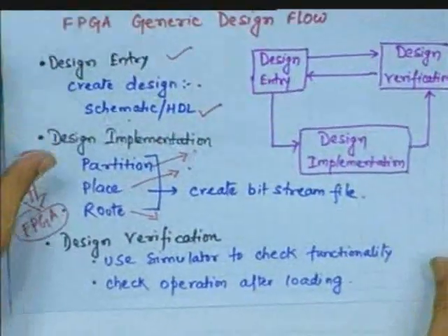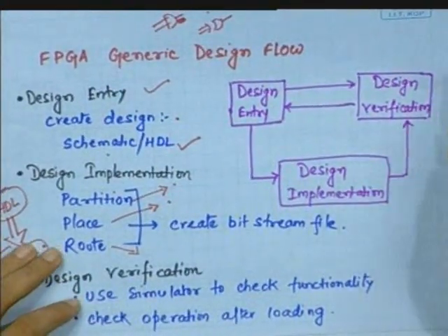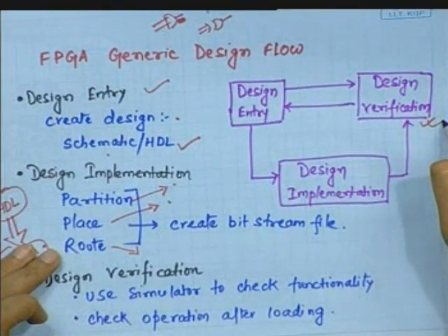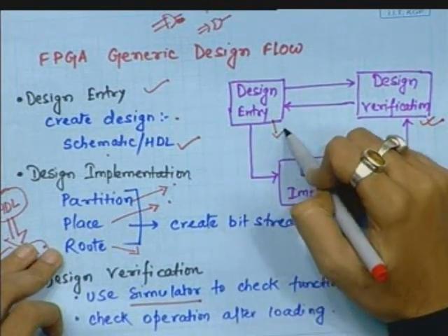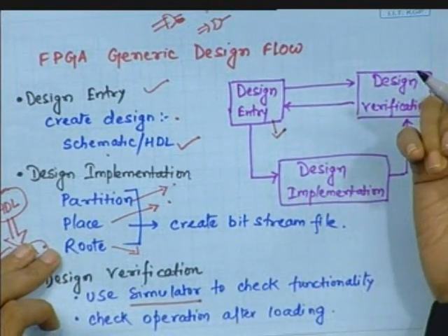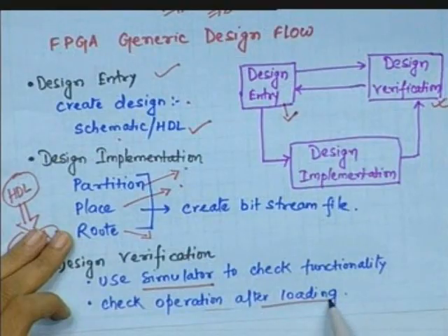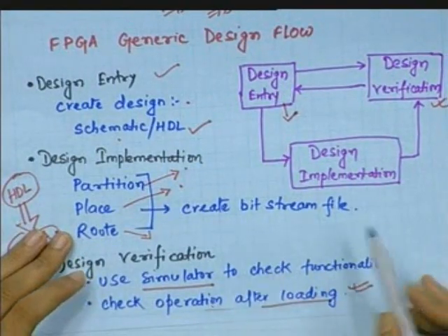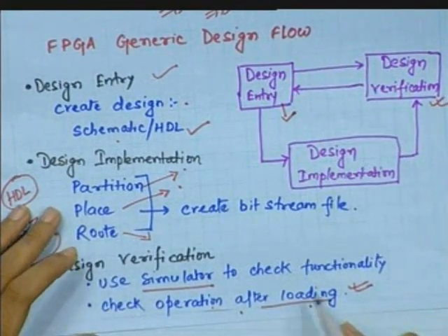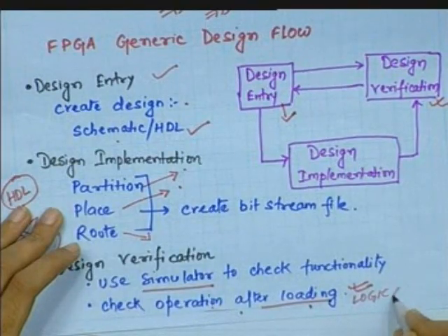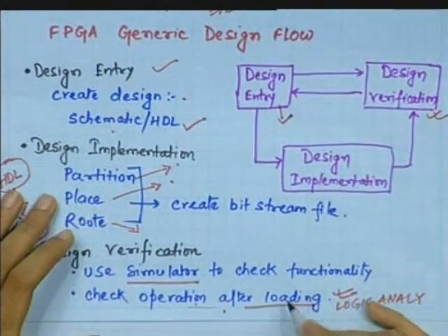At the same time, when this design flow is going on, you should go on verifying your design at every level. You can use a simulator at the design entry level, such as ModelSim. You know ModelSim, I hope. Or check the operation after loading. You have seen the operation of an FPGA after loading, where? Yeah, the logic analyzer. The functionality and the timing parameters were all tested after loading.